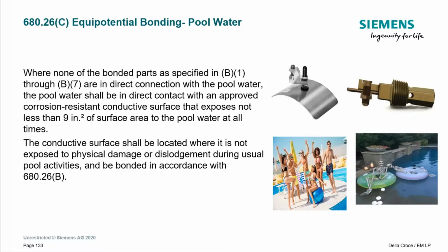I haven't dealt with this as an AHJ. Anything you introduce here, like the piece in the skimmer or that piece that threads into the T, has to be listed for this application, and you'd have to follow the manufacturer's installation instructions like we talked about. So with that one that threads into the T, when you look at the installation instructions, the manufacturer basically says it has to be installed below the normal water level of the pool. So it actually has to go underground in the plumbing system. Then the manufacturer also says you really need to leave an access box to get to it.